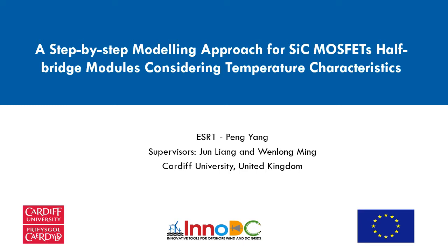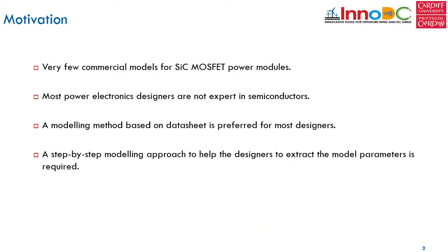Today I'm going to talk about a step-by-step modeling approach for silicon carbide MOSFETs half-bridge power modules by considering the temperature characteristics. When designing power electronic converters using silicon carbide MOSFETs, the device models are usually required to simulate the performance of silicon carbide MOSFETs, such as switching losses and EMI.